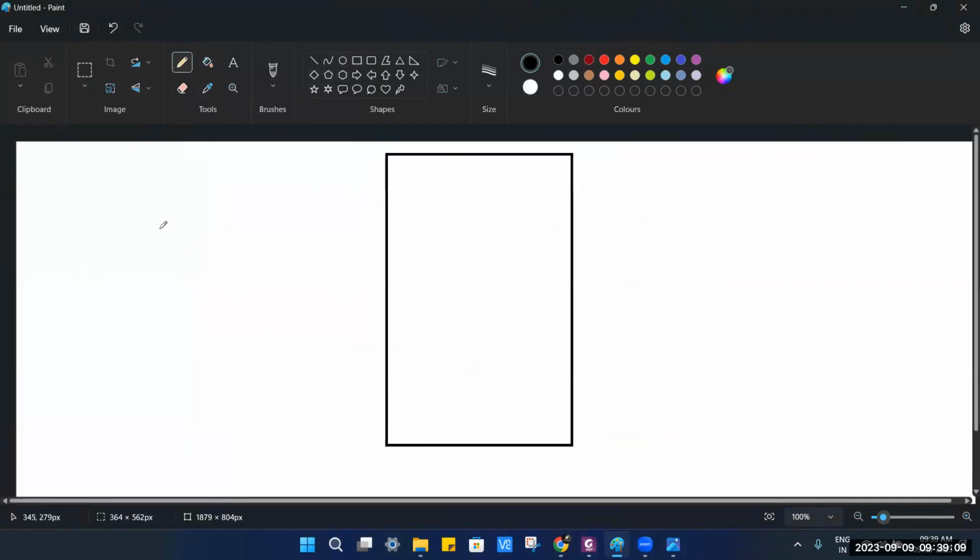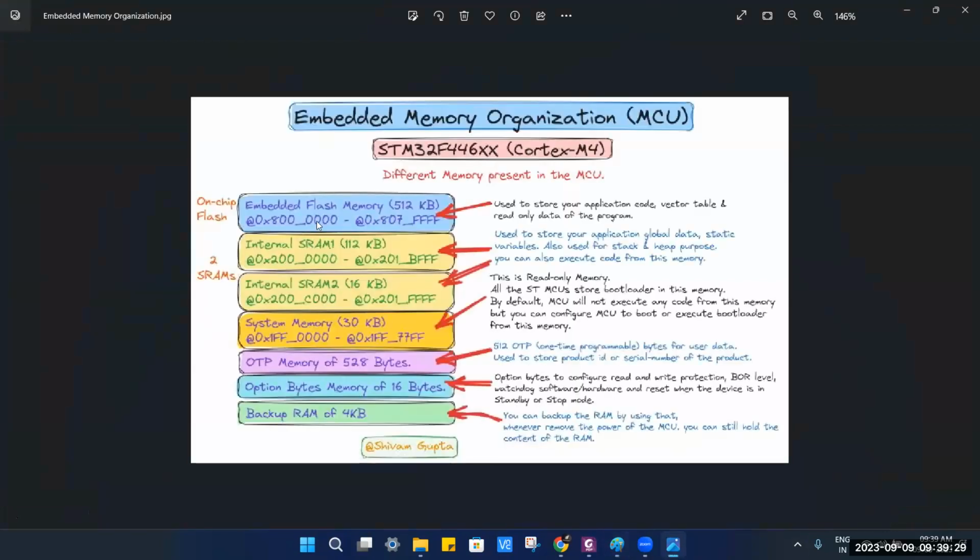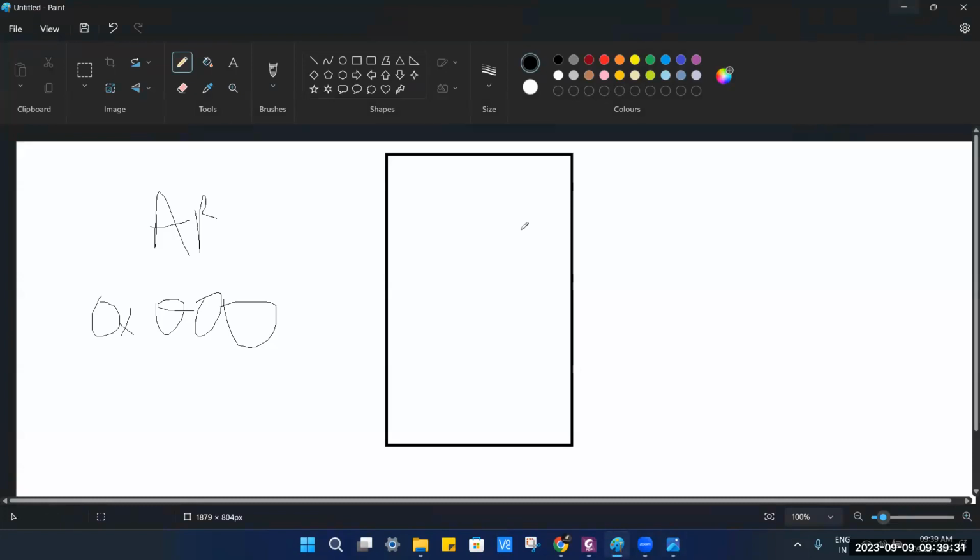So actually this has been defined in the ARM architecture. Whenever we do the power on reset, the processor reads the value stored at the address 0x0000. But you might have seen here they have mentioned 0x08000000, right? But the ARM architecture will read it from here. How this mapping is done is by aliasing, memory aliasing. Okay. I know.